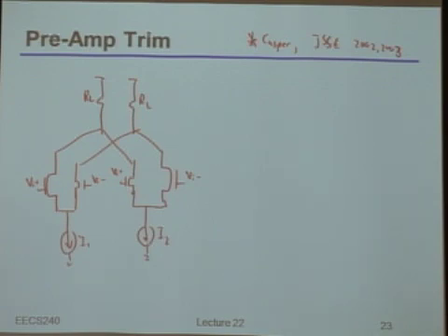So as I said, the good thing about this is that it allows you to always use the bias current, right? Because either way, you've always got that bias current giving you some kind of GM. And by the way, just to make sure it's absolutely clear, the way you generally use these things is you keep the total bias current fixed. You just move it from one side to the other. Okay, so if you wanted a more negative offset, you move it over here. You want a more positive offset, you move it over there.